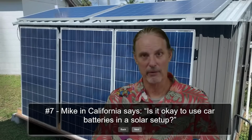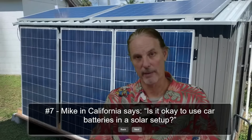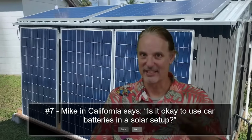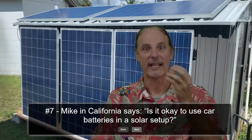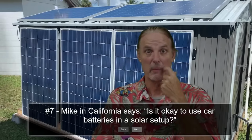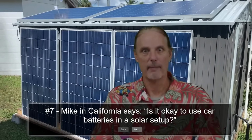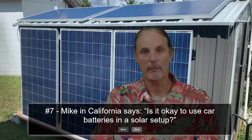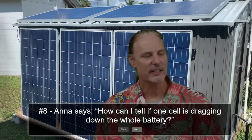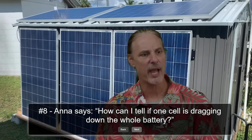If you have a lithium iron phosphate at 100 amp hours, technically you can use all of the power that's in that battery. The only thing you've got to be careful about, as we're talking about here, is the state of charge needs to be accurate. And calculating that from a lithium iron phosphate is much more difficult because you can't just use the battery voltage to really determine how much energy is left in your battery.